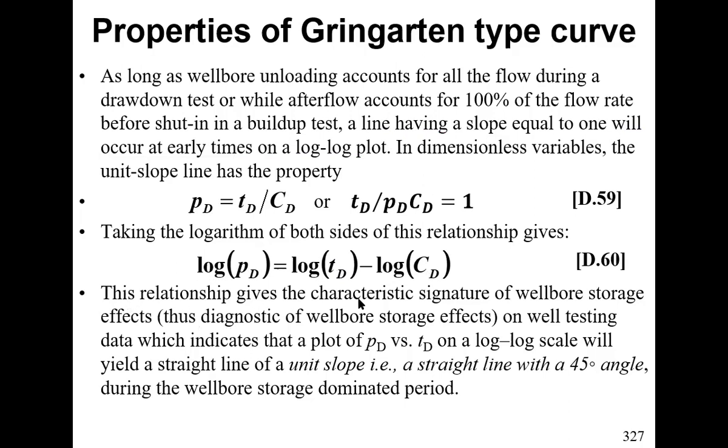This relationship gives the characteristic signature of wellbore storage effects on well testing data, which indicates that the plot of dimensionless pressure versus dimensionless time on a log-log scale would yield a straight line of unit slope during the wellbore storage dominated period.